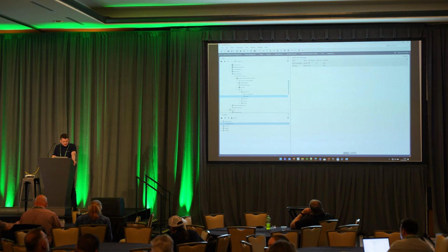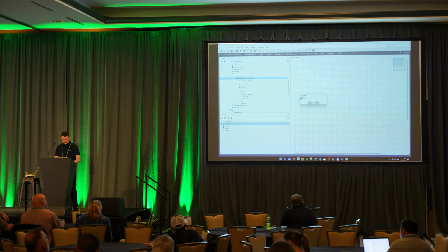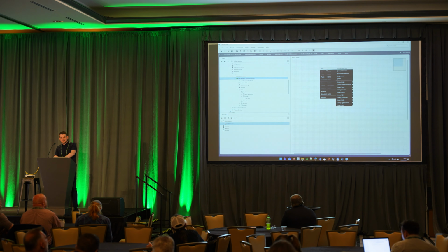All right, so let's go back and do some demo here. So we have our zone equipment, and right now we are in our nano controller connected over the USB. So we'll create our first equipment, and it's just right click. We'll call it VAV1. You can see that when you right-click on the wire sheet, you will have a dedicated menu just for our nano devices. So when you click and add the data point or a binary data point, it's coming from our nano system. It's not a Niagara proxy point.